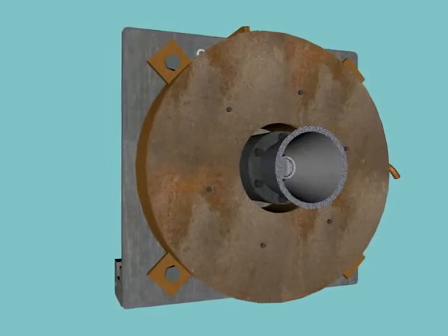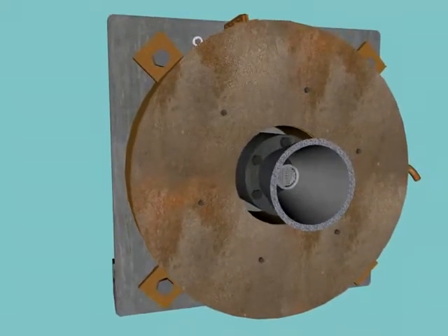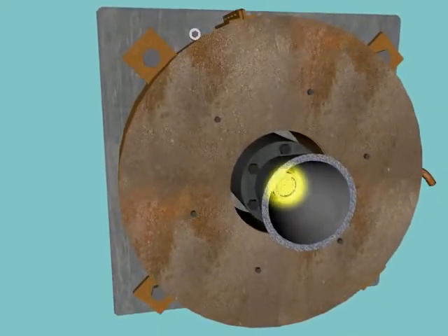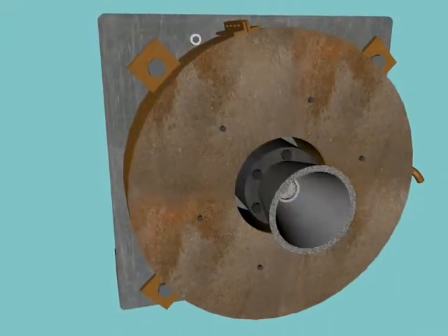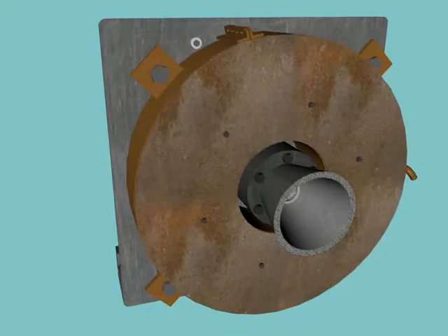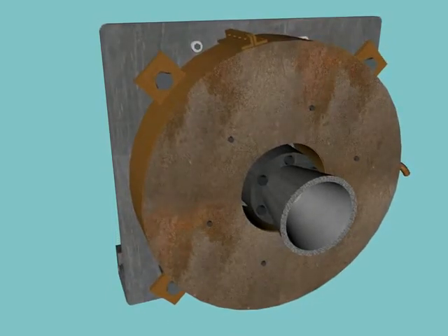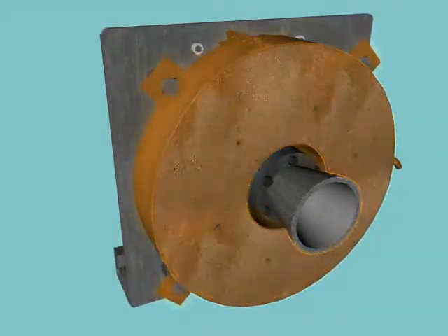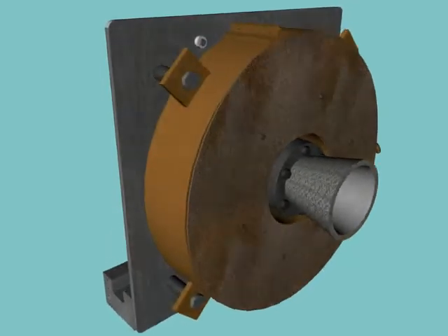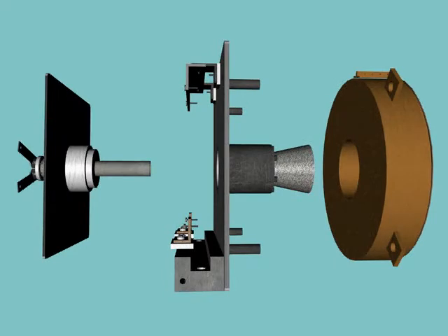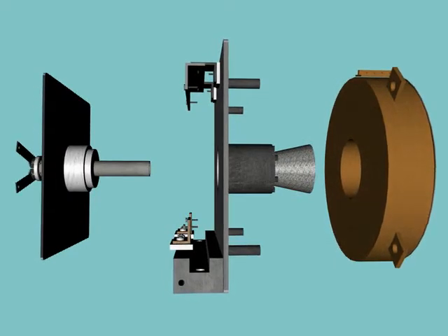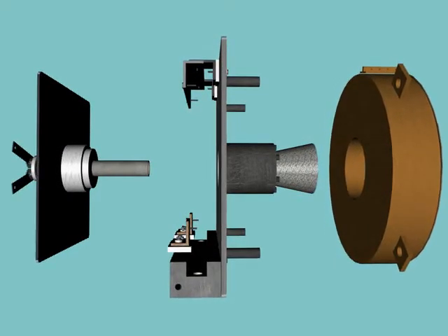It contains many parts and uses many subsystems. At the center is the cathode. Around it, the anode, which is also the thruster's nozzle. This is an applied field MPD thruster, and so has a solenoid. The Lithium Thruster can be roughly divided into three parts: the anode assembly, the cathode assembly, and the solenoid.